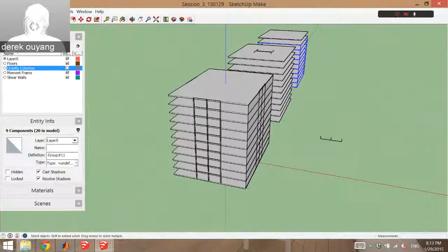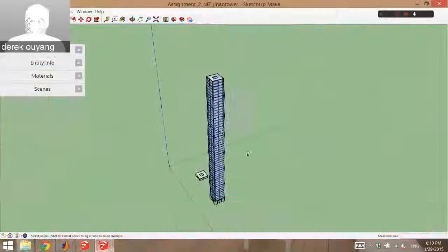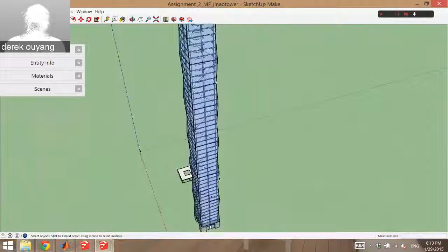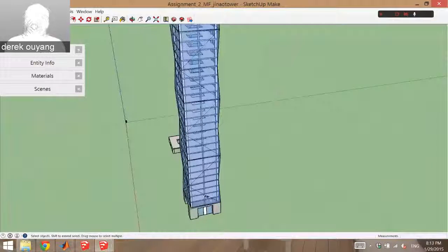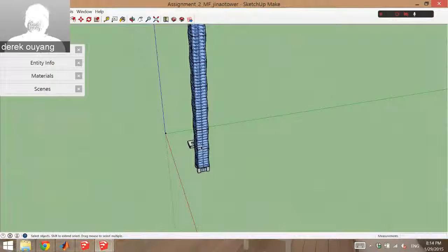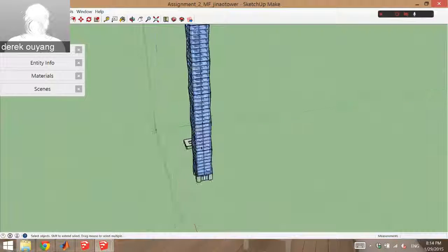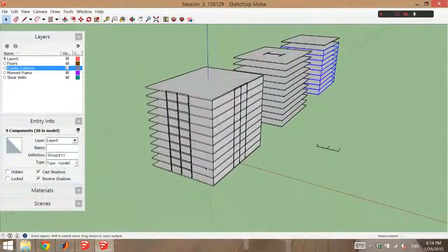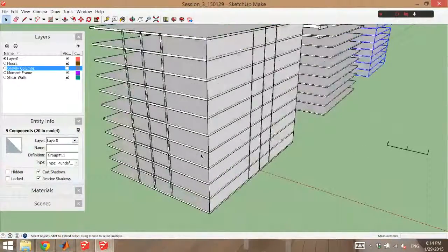Yeah, and in design, you're going to be the most constricted on how far you can go. So, for example, this tower is screwed, right? Actually, it's screwed in both directions because it's a square. But imagine that same tower, and you don't have the affordance of a wide width to your bending moment, right? You can't deal with moment by having a lot of compression in one column far out and a lot of tension in the other one. You're going to actually have a lot of bending moment on each column. So for that tributary area, we just take the side that we're hitting and half it.